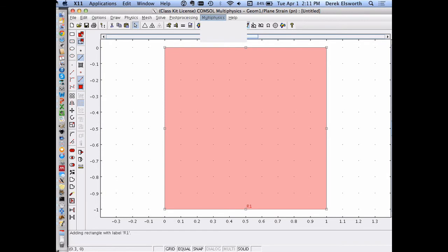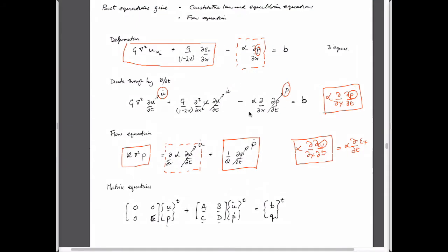So what we'd like to do in this first expression here for the solid mechanics equations is we'd like to have a term that would represent alpha B0 times pressure changes in space and time. And so the actual component would be, I think, the way that COMSOL does this is it has a concentration, which it defines as this variable.